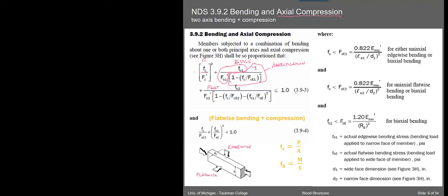And the force is coming straight down it, so the force is actually offset by some delta distance from that center point. That offset then causes a force times a distance. It causes a moment, which means it bends even more. And as it bends more, it deflects more, and that can escalate and cause failure.